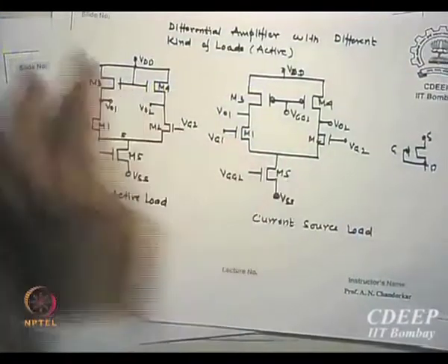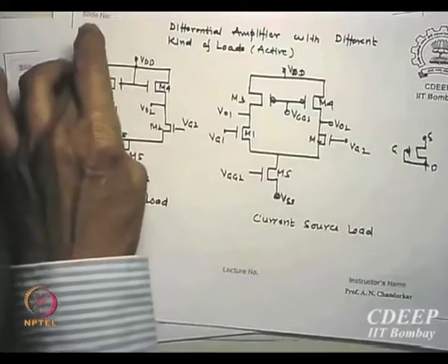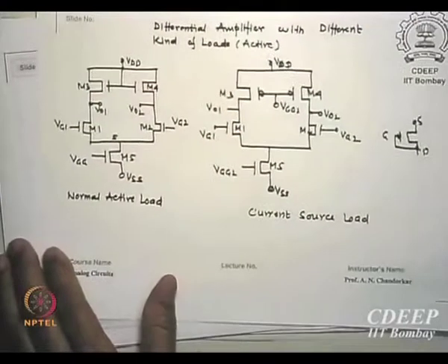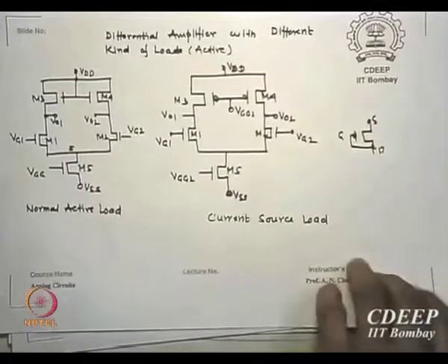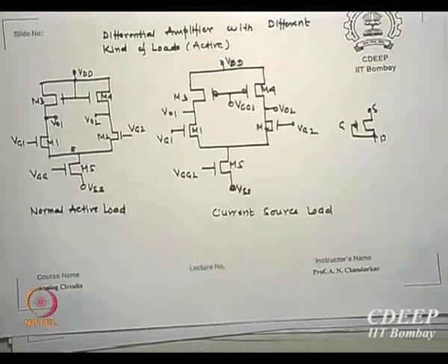So essentially this means that I can fix the difference gain by what should I do in this figure? I should adjust the size of M1, M2 with reference to M3, M4. The ratio of these. Why I am stating I did not take lengths, because lengths in all transistors will be identical unless said otherwise. Lengths of all transistors will be the smallest channel length available to you. Is that correct? All integrated circuits in analog use common channel lengths for all the transistors, so is in digital. Channel lengths are never changed.